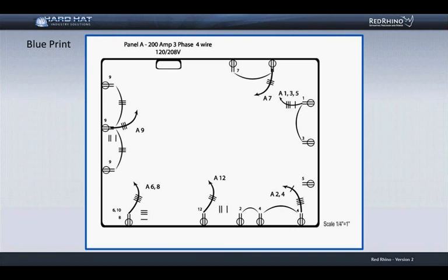The drawing shows a top view of a building containing one electrical panel with branch circuit conduits feeding receptacles on the wall. There are several different sizes of EMT conduit, plus 12-2 and 12-3 MC cable runs. I will demonstrate how to take off the conduits and transfer the information to Red Rhino.